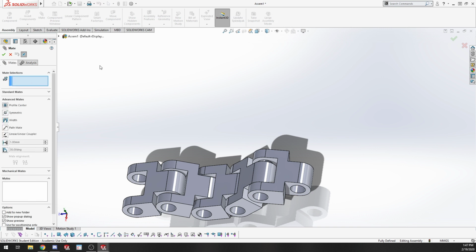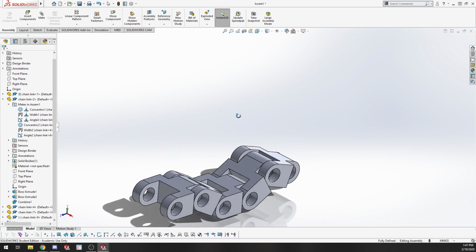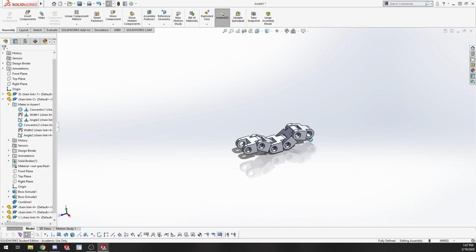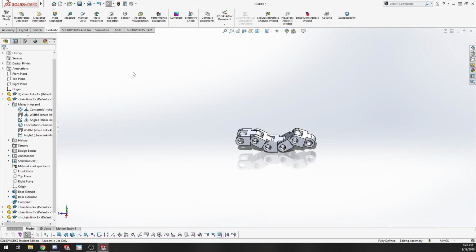Yeah. So that's mates. Mates are pretty much the biggest thing within assemblies. I'm going to be spending a fair bit of time adding those in once we start to build that full car model. You're going to drag the chassis in, start adding suspension points, or suspension arms, and pulling them in there. You're going to have the points able to move around in a bunch of different directions. Then you might define them to be between a certain angle, so you don't have your wheel up on top of the car. Right. Yeah, and then other than that, there's a couple of neat tools within